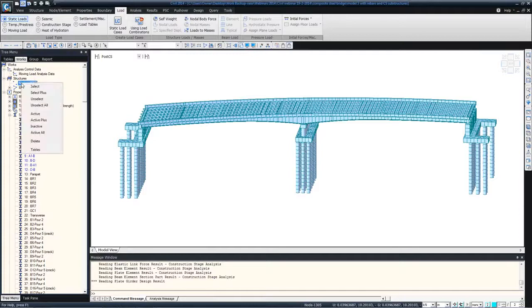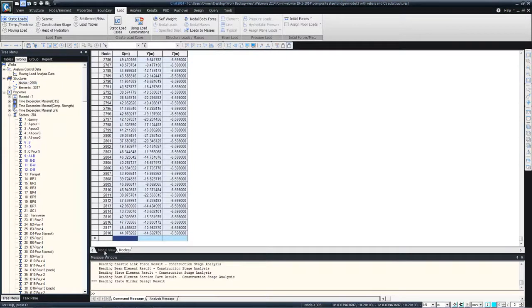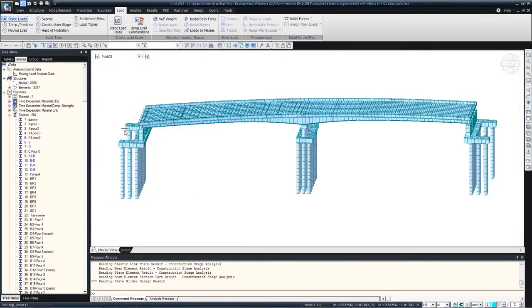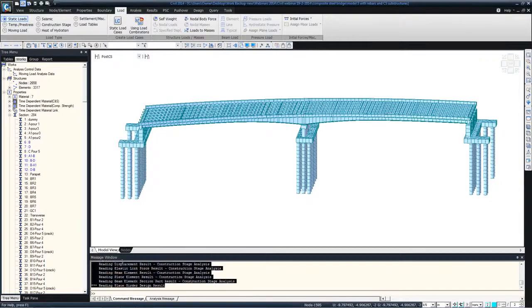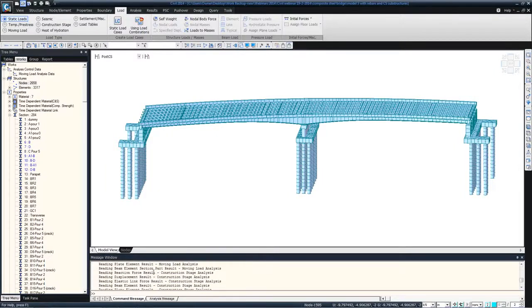Then you can also look at tabular data entry, like the nodes table, for example. Again, these are Excel compatible. And then you have a message window here which displays some warnings or errors if you have committed any mistakes in the model. And a command line is here, so you can type in commands like create elements and similar commands like that. It will prompt you towards the nearest command.